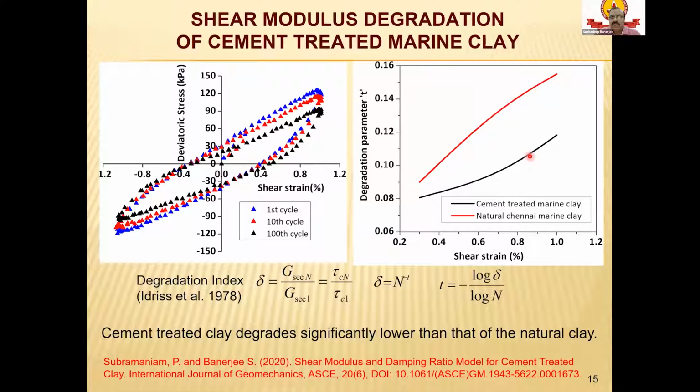But the thing we have to note here is that it's not zero degradation. That means even for a cement treated clay, degradation still persists. So the assumption that there is no degradation of stiffness with cyclic loading for a cement treated sample is not valid.